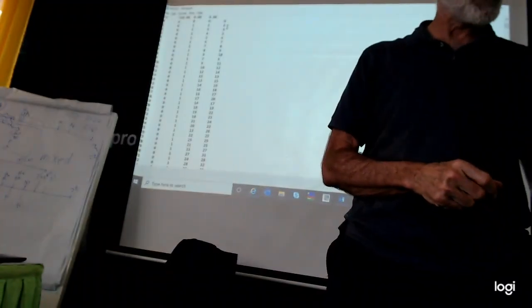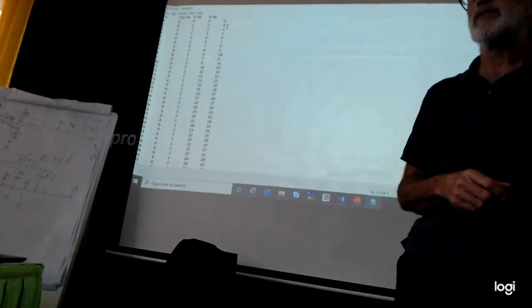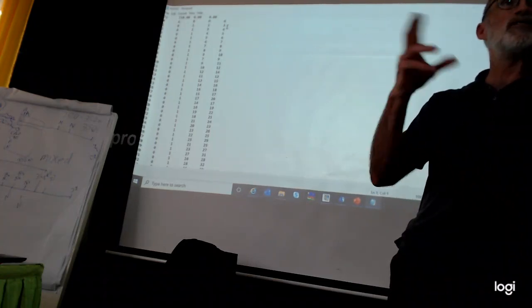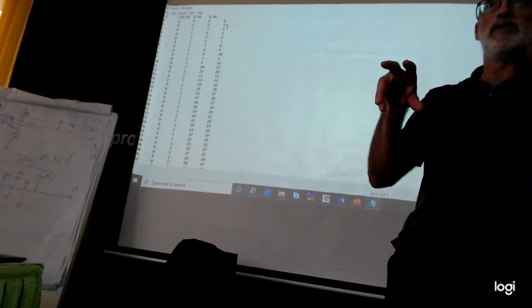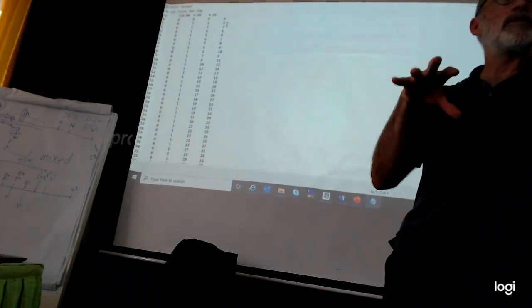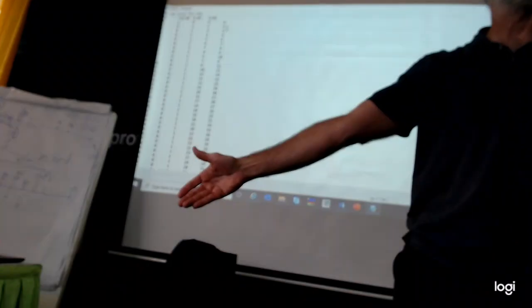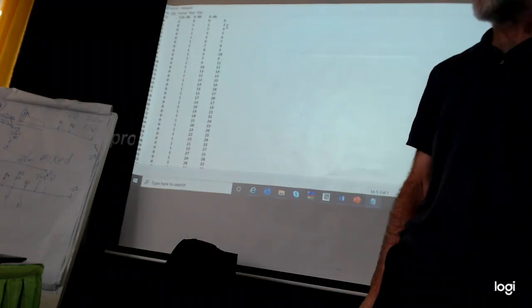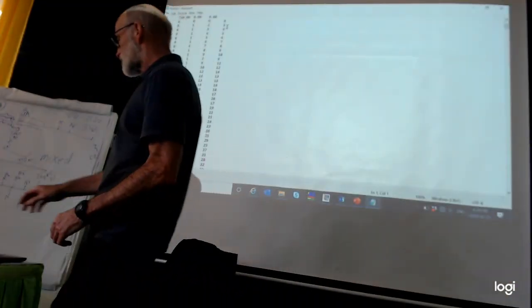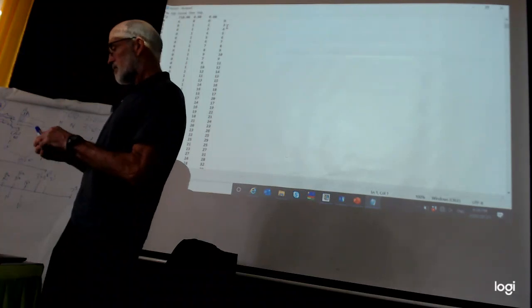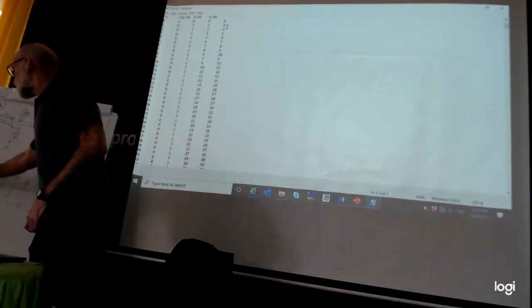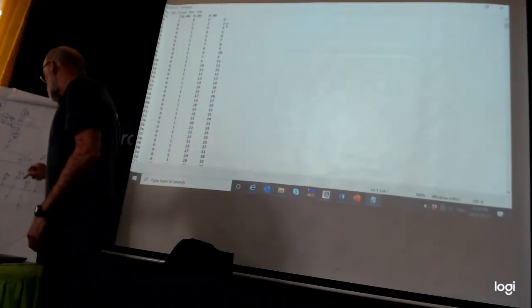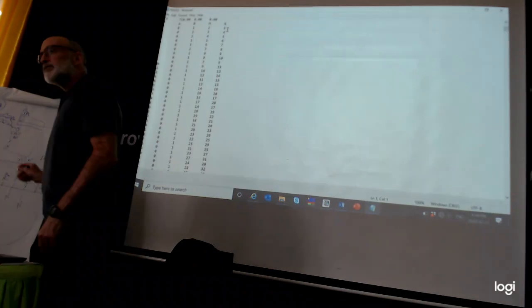And the reason why we did that was because we knew we had a 200-meter deep aquifer and we wanted to see deeper. So having this very remote electrode caused the current to go deeper and come back up to CB, wherever CB was.